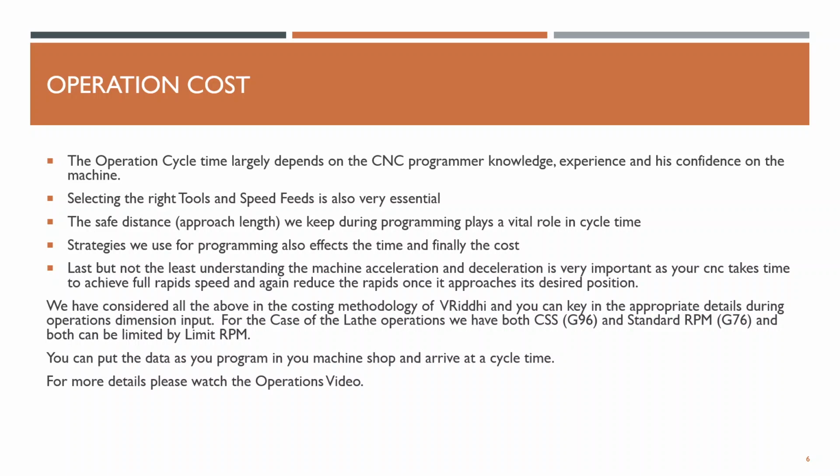One of the important factors where most people fail is understanding the machine acceleration and deceleration. Frankly speaking, this plays a very important role, especially if you are not planning your to and fro movements properly. We have provisions for taking the acceleration of the machine into account, and this helps us get closer to the non-machining cost, I mean the rapid non-cutting time. So all these things we have considered very properly.